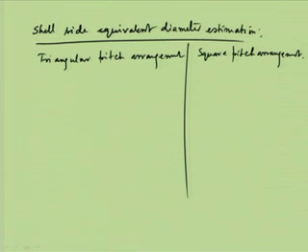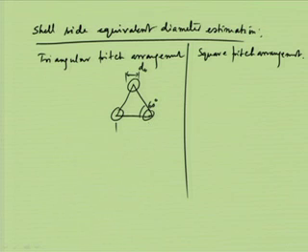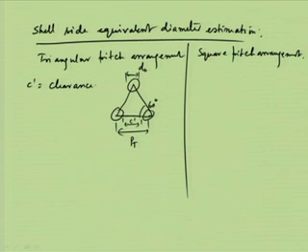In the case of triangular pitch, it is also called the 60-degree triangular pitch, because it is an equilateral triangle. We have seen this several times, it is not the first time we are discussing it. This is the outside diameter of the tube, and this is the 60-degree angle, so an equilateral triangle. This is nothing but the tube pitch, and this part is the clearance, C dash. So, C dash is the clearance, and PT is the tube pitch.